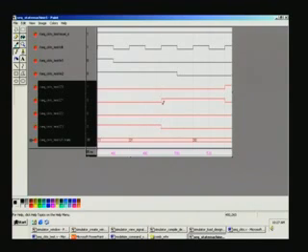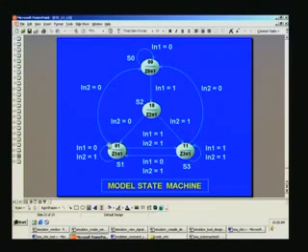So any sequential machine will have this, always delayed by a clock. And that's not a handicap, because we always have a very high frequency for the clock, and no user can notice the difference. And no erroneous operation can take place, because the whole thing is synchronous as such. And here, that's what we have from S1 to 0 0, provided both inputs are 0, and you can see that here, right?